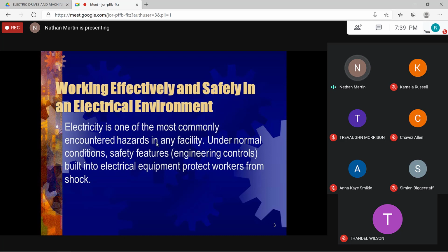When you buy a brand new one-bolt clamp, some one-bolt clamps come with a little grease inside it. That grease really serves the purpose of locking out the moisture from the conductor, right? And because the conductor is aluminum, after a period of time it tends to oxidize, right? And lose it and have a build-up of resistance there. And that build-up of resistance is what causes the voltage drop to be high and you are not getting the proper voltage inside the panel.